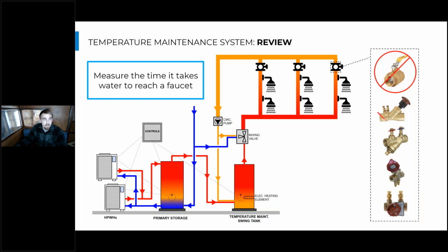And so we also talked about the temperature maintenance tank and how this water needs to be heated in a special way when paired with heat pump water heaters, because heat pumps typically don't like to reheat this warm water up to a high temperature. They like to heat really cool water up to a high temperature, and that makes them operate a lot more efficiently and reliably.